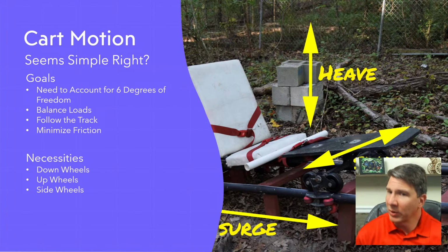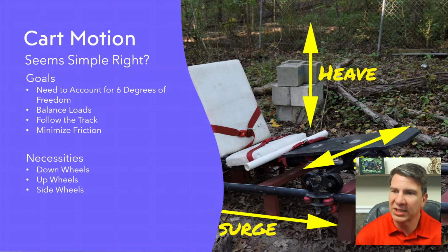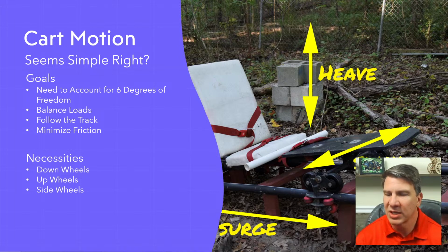Well, for one reason, we want to balance loads. When I look at the rear axle, where I'm more heavily seated on, that's going to have higher loads. I want my loads to be even so that I can distribute that over 2 sections of my PVC pipe.